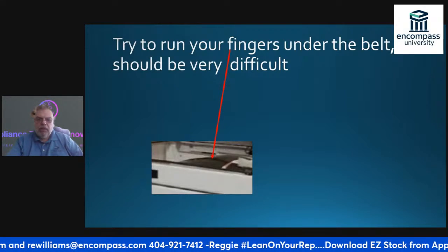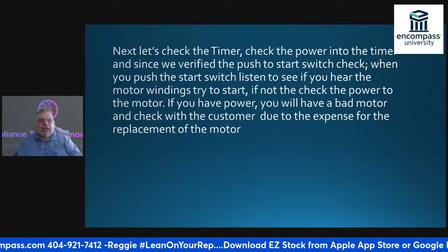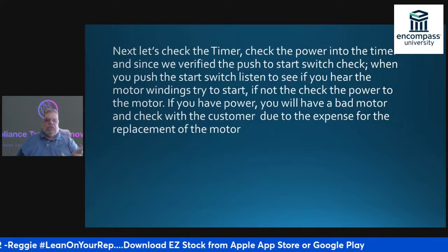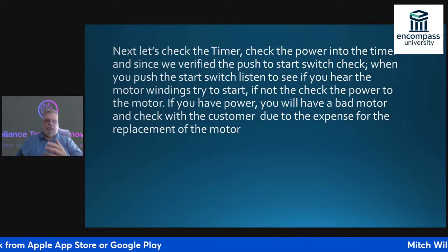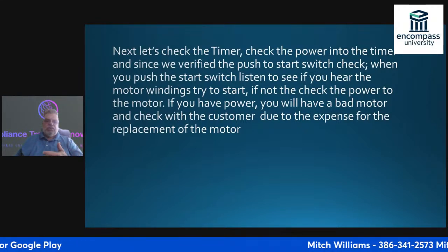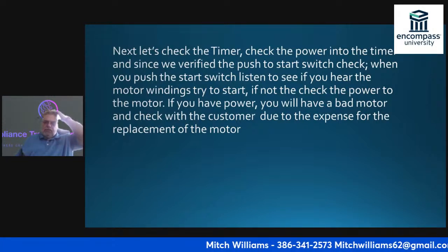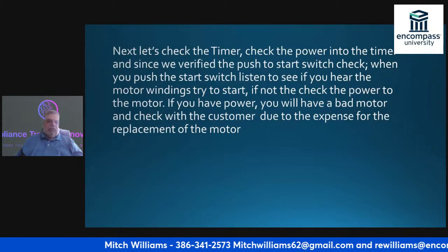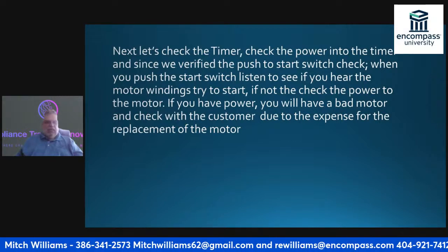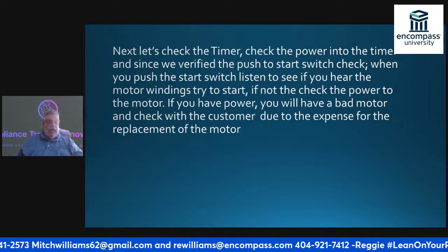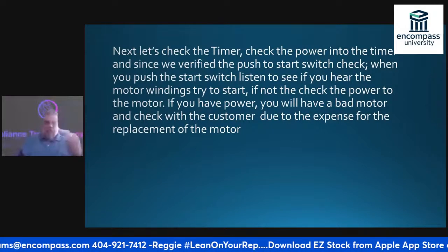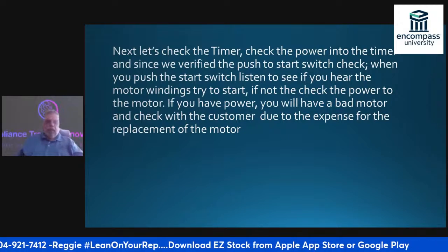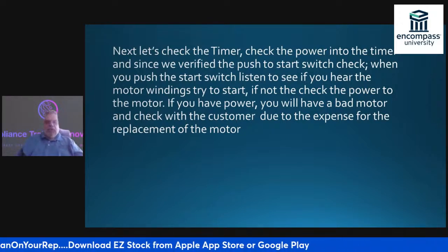Okay. So if this all works, I'm going to have to check the timer. I need to check power to the timer. And since we verified the push to start switch, then you push the start switch and listen to see if you hear the motor windings try to start. If not, check the power to the motor. I can do that by pulling the wiring schematic again and finding the wires that go down to the motor.